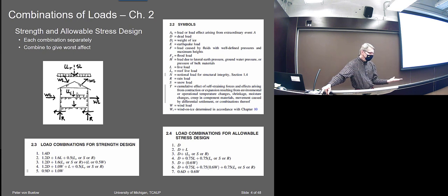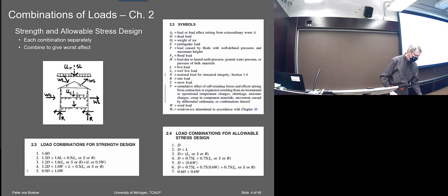And wood is a very lightweight material, really. So the dead load represents a smaller portion of the total load, and there's not much advantage in using the LRFD. You don't benefit very much from it, if at all. So for a long time there was no LRFD version, and then I guess, I forget which code, a couple of codes ago, they added the possibility to calculate it with LRFD, and we'll look at that.